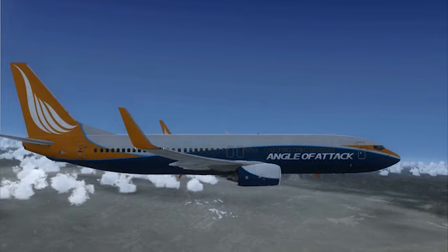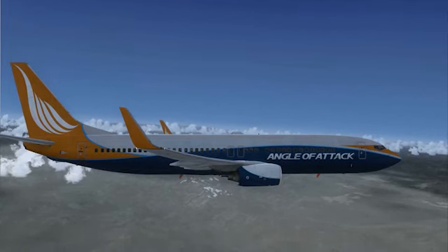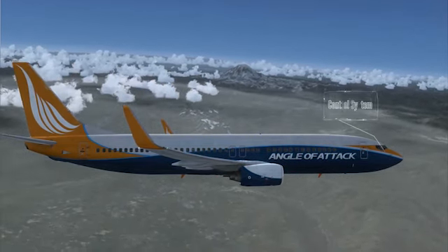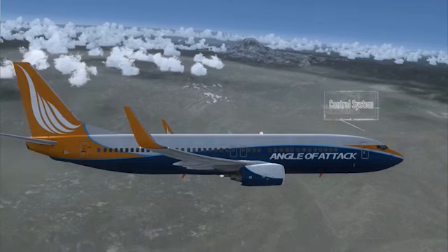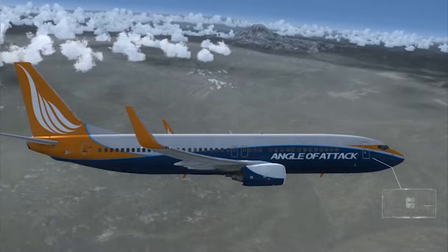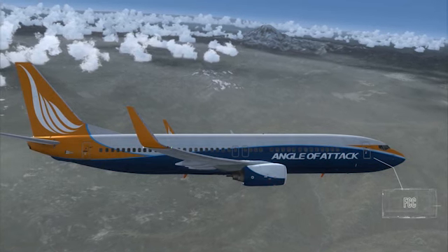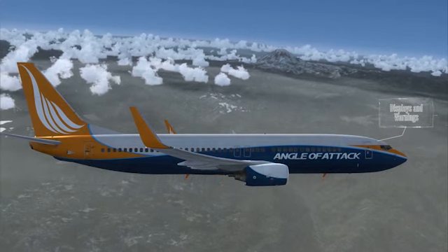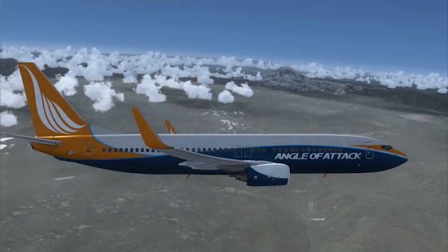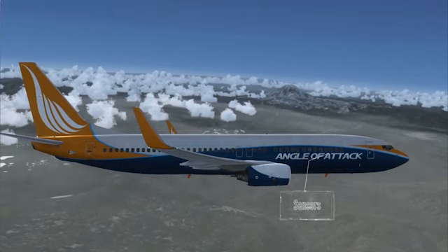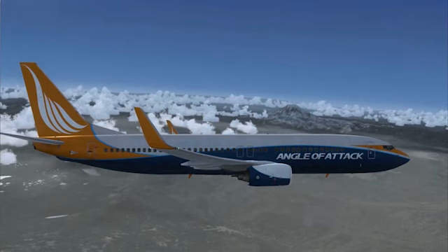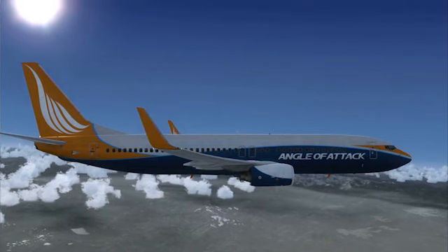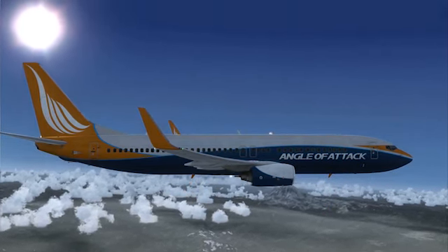The Automatic Flight System, or AFS, is a suite of different components that allows the pilot to get guidance through indications on the displays, or the ability for fully automatic flight. No one component acts on its own to control the others. Rather, it's a digital, analog, and mechanical symphony that allows for smooth, efficient, and automated flight control. Everything else we talk about in this autoflight lesson will be assumed to be encompassed by the overall subject of the AFS. Consider AFS the mothership of autoflight. For simplicity reasons from here on out, we'll refer to AFS as simply autoflight.